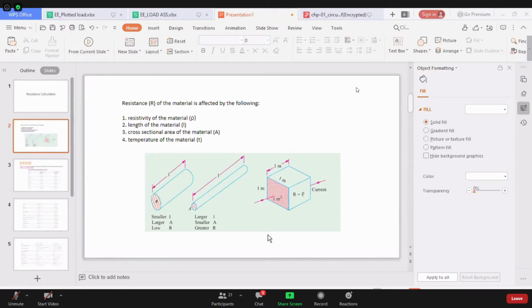In such a way that, because of the resistance in the wire, when it reaches your load end, the voltage is very small. No? So instead of the 12 volts you require, when it reaches the load end you only have 9 volts. So it is not enough to run the load, which requires 12 volts. So that is why it is important for us to know how much the opposition is, so that you'll be able to adjust.